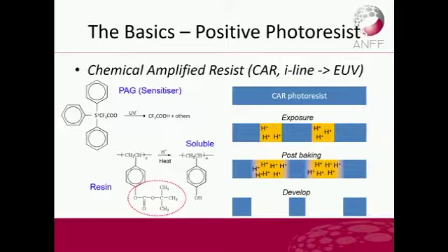So one of these PAG switches can actually initiate quite a few of these polymer deprotection mechanisms. That's why they are so popular in the IC industry, because the sensitivity or the dose required to pattern this resist is significantly lower than the DNQ process.